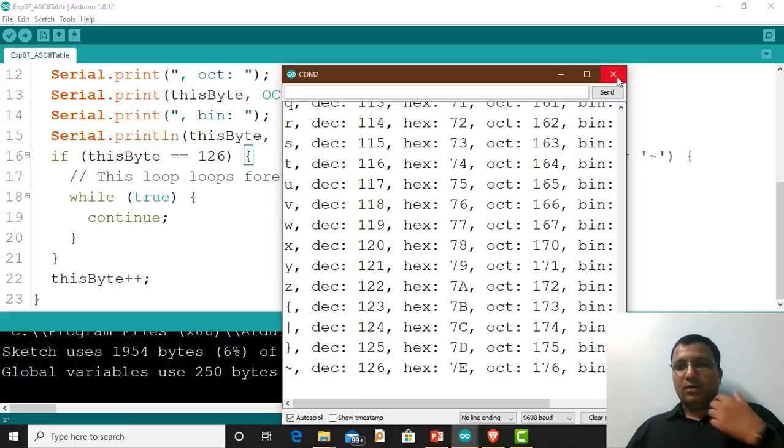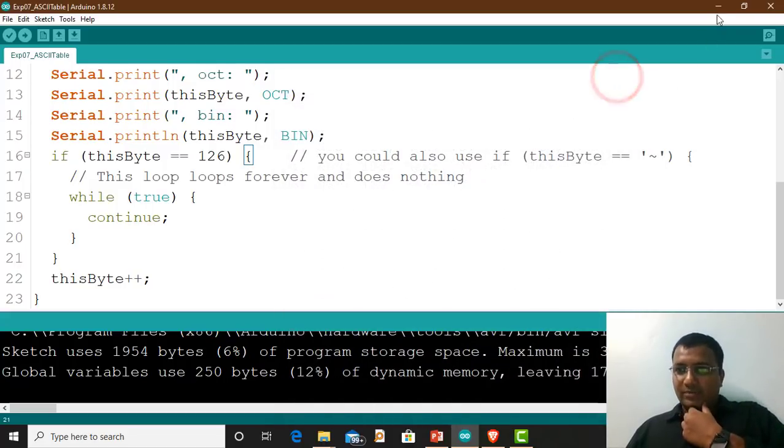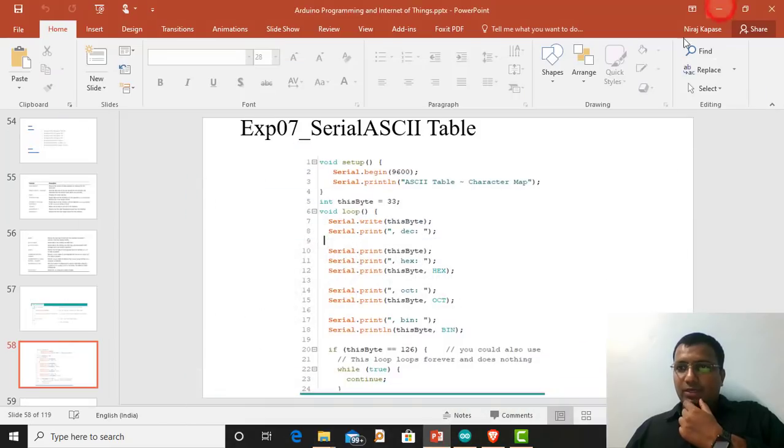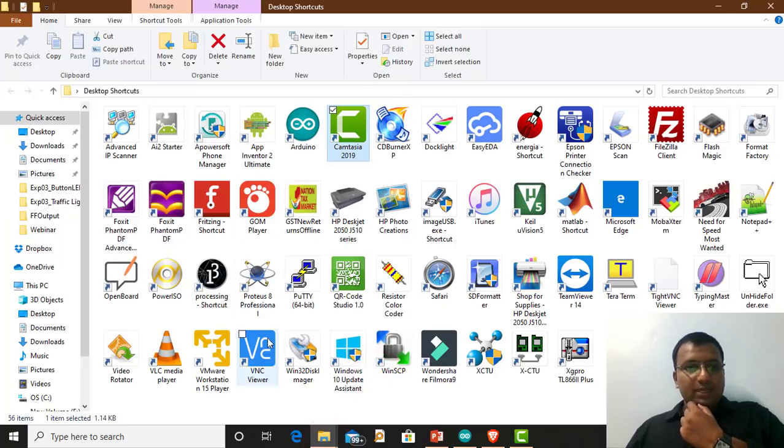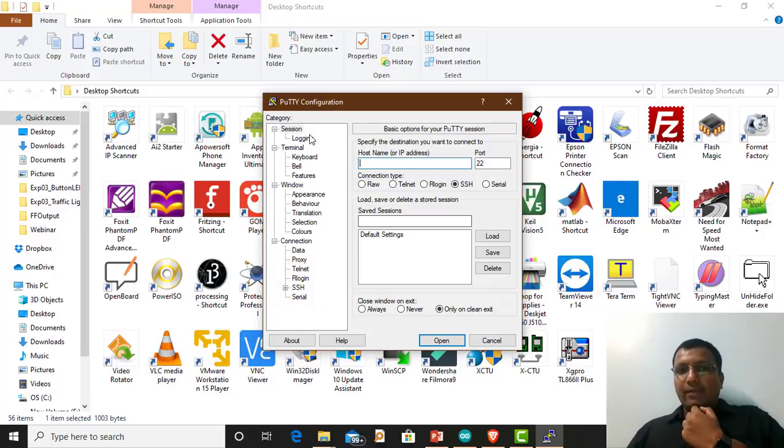Now there are different open source software tools available for the serial window. So I'm going to demonstrate those as well. We'll minimize this, maximize this. So the first tool is PuTTY. PuTTY is a tool again for the serial window configuration, and we can have different logging. PuTTY is a very popular tool for internet access or Ethernet access, or we can have SSH, Telnet or Rlogin, remote login we can use via PuTTY. So we can do serial configurations as well.